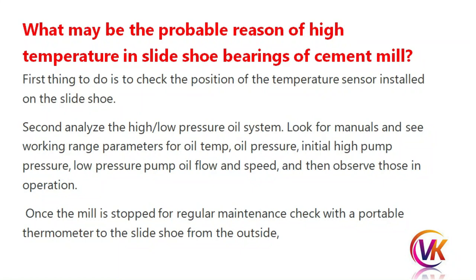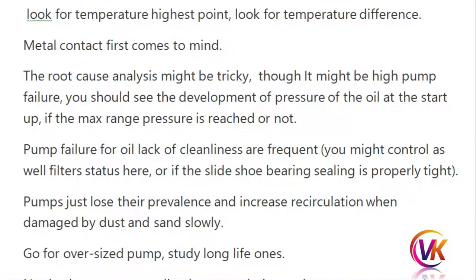Once the mill is stopped for regular maintenance, check with a portable thermometer the slide shoe from the outside. Look for the temperature highest point, look for temperature differences. Metal contact first comes to mind. The root cause analysis might be tricky, though it may be high pressure pump failure.